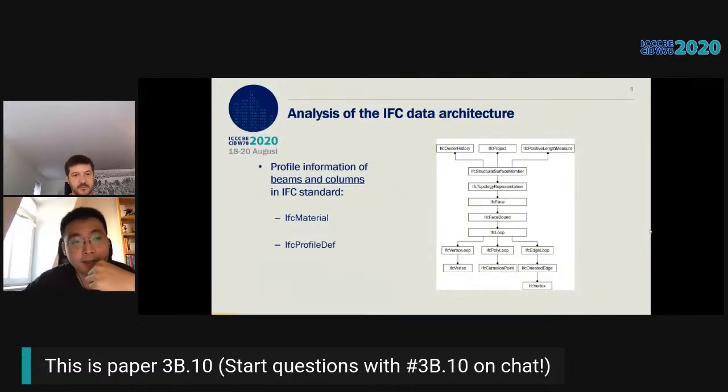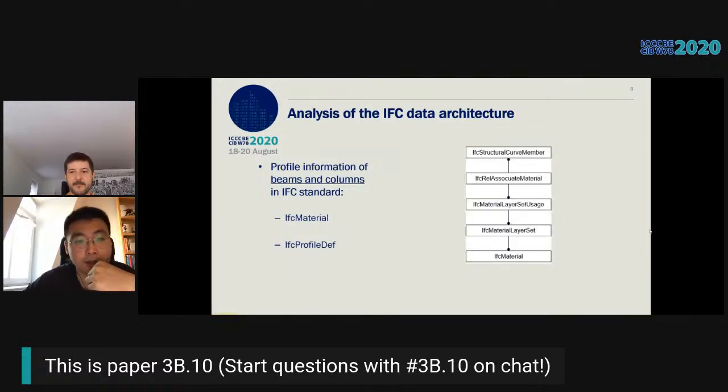Next slide. I made a mistake here. This should be the geometrical definition of 2D building elements like walls, plates, and slabs. There are 3 different ways to define a 2D building element in IFC standard. However, all of them finally go to the loop of either vertex or Cartesian points, so that the shape and the direction are defined at the same time.